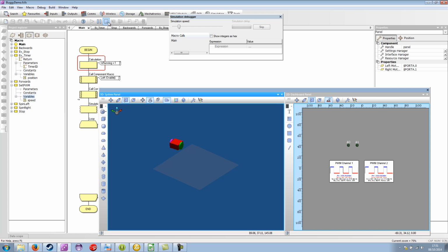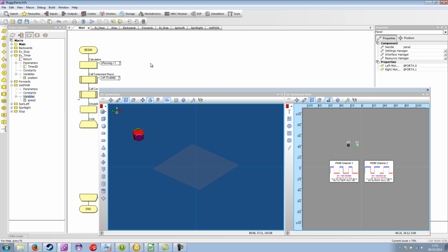So there we've added some on-the-spot rotation, and also we've added code that will allow this to actually work on physical hardware. As opposed to PWM components, you could use servo motors and mod the inner workings of the servo so it provides constant rotation rather than positional control. That's very good for a motor drive for a buggy, but I'm going to keep my example for PWM for the rest of these series.